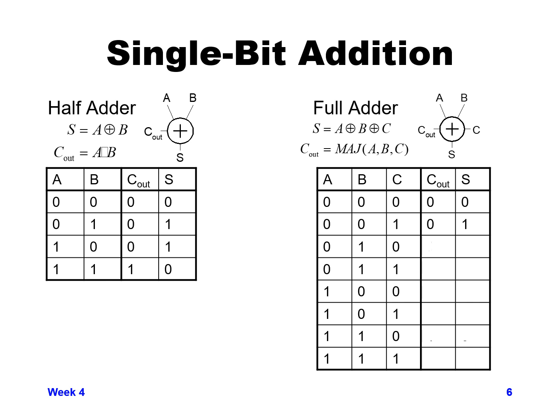The same is true in the next case, where only B is a 1, so only one of them is a 1, so you should get your sum of 1 but no carry out. In the next row, you have 2 1s, so now you have a majority that are 1, so you should get a carry out, but your sum will be 0 because you only have 2 1s, and an XOR of 2 1s gives you a 0, and then XORing it with the 0 stays 0.